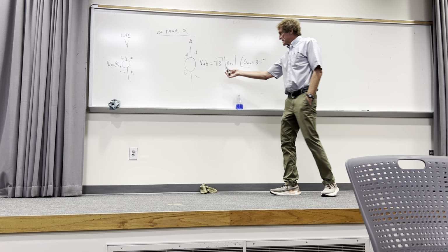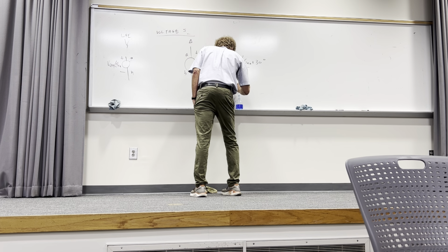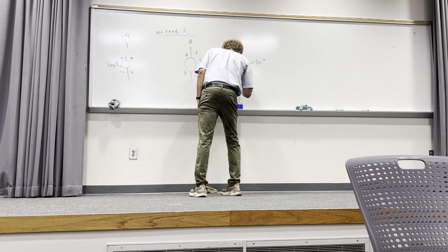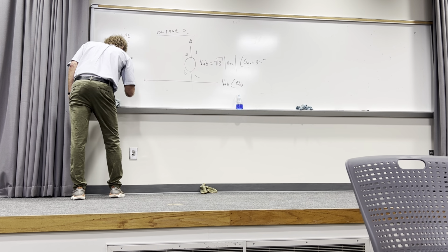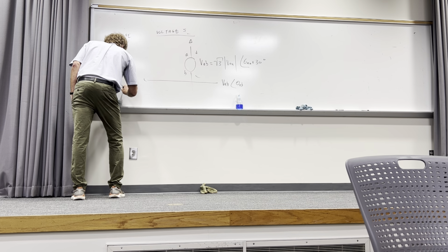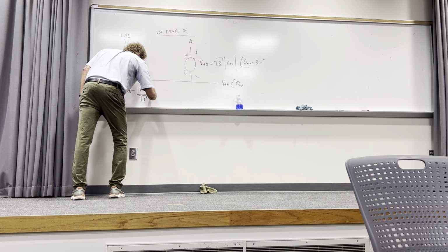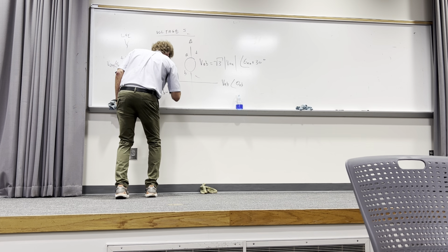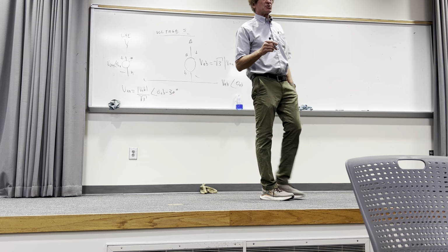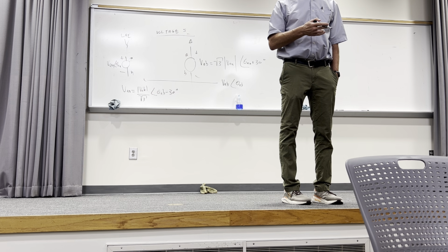If you were given a delta voltage, for instance, if you were given VAB at some angle theta AB, and this is the delta configuration over here, VAN would have a magnitude of VAB over the square root of 3 at an angle of theta AB minus 30 degrees. Now I want to be clear about that. That is the relationship between delta voltages and Y voltages.